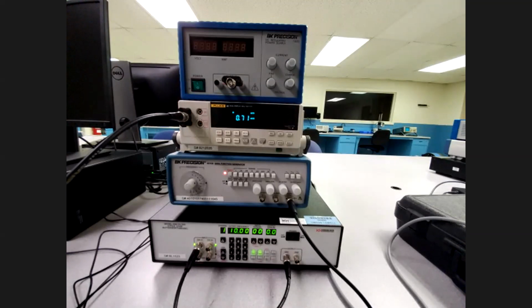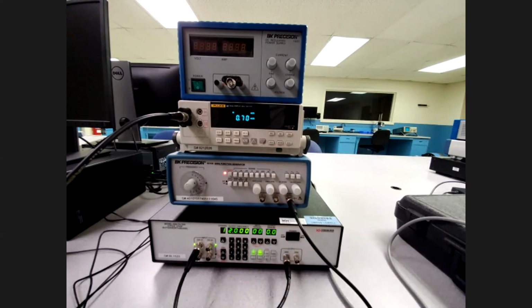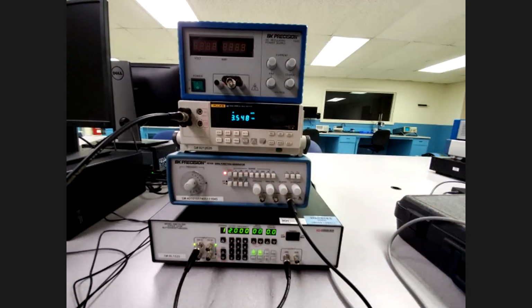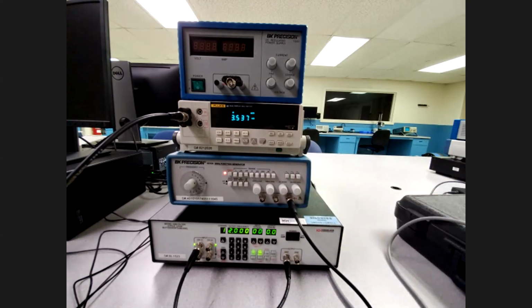Okie doke. So the only thing that we need to make sure is that the unfiltered signal is 5 volts peak. We are at that because that was the same magnitude that we had for the previous assignment, because we never changed the output level from the function generator. I'm just gonna decrease it to 5.3 to get closer to what we should have.